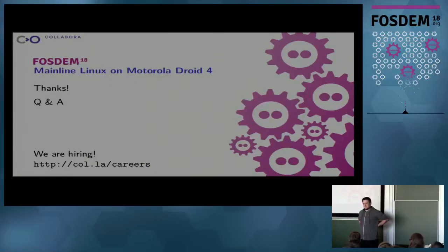The OMAP 3 camera in mainline is not that good. Yes, but it's working. On the N900 we got pictures from the camera with the mainline kernel. If you do not do something right, I've seen a lot of kernel hangs these days because of that driver doing something weird. That's a nice place to debug.